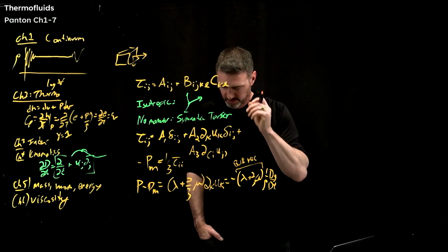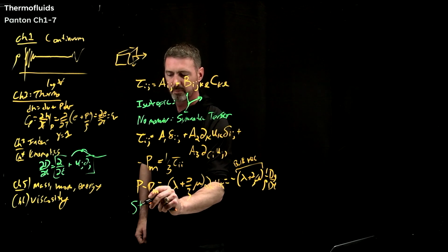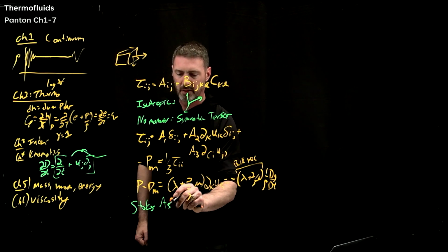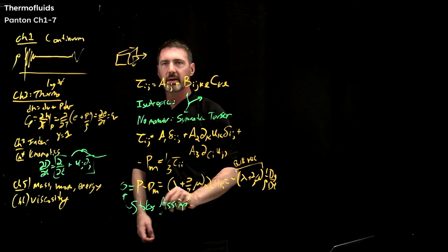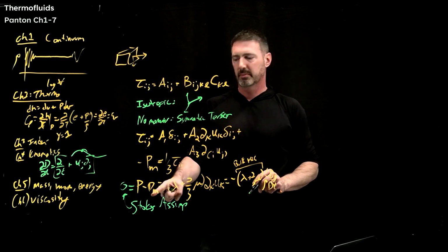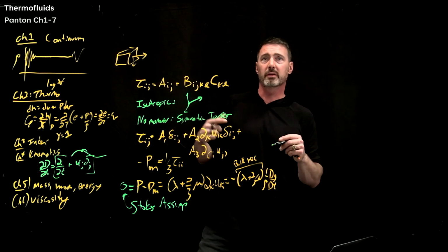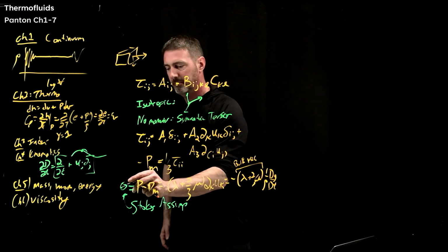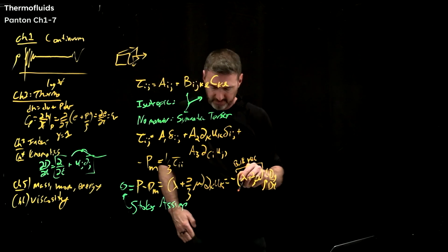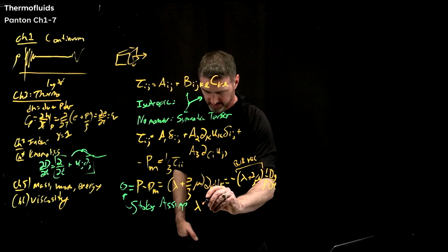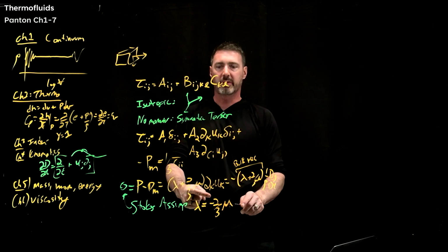And then the next assumption is called Stokes' assumption, which is basically saying that the thermodynamic pressure, the one we would associate with a thermodynamic state variable, back to our thermo, that's why I'm teaching this together, and mechanical pressure are the same. What does that force us to have happen? Well, that forces lambda to be equal to minus 2/3 mu. That's what the Stokes assumption drives.